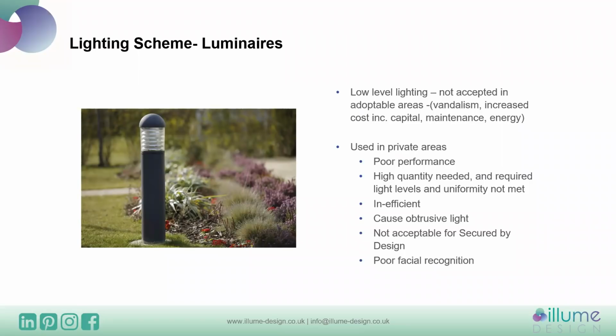So in terms of luminaires, low-level lighting, so this is a very typical bollard, which is something that I really don't advocate. It's not accepted in adoptable areas because it's very prone to vandalism. There's an increased cost to purchasing these. You need a lot more to light an area. They have a very poor performance, and they cause a lot of light pollution because light is directed at 90 degrees out from the light source.